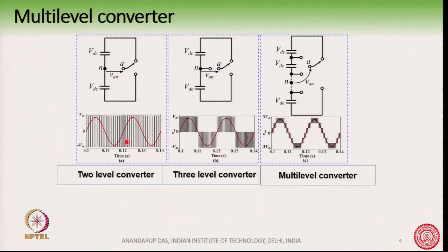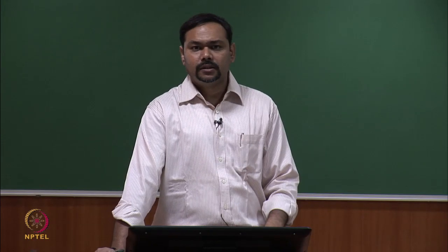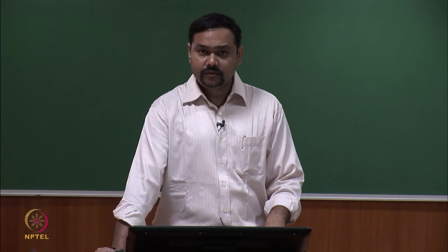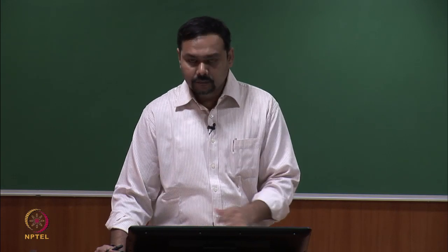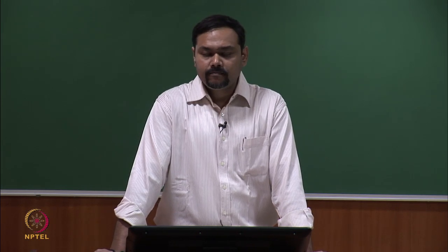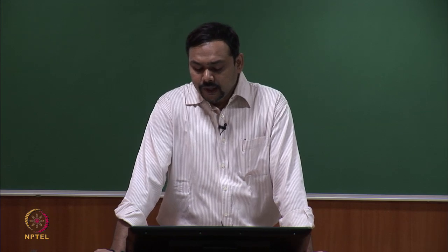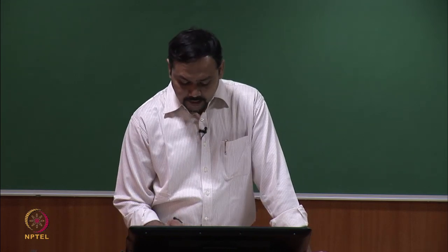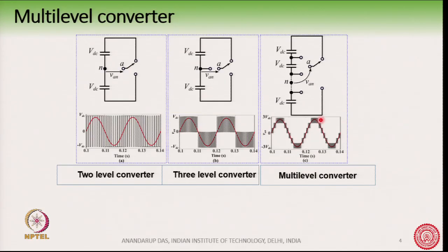We can get a voltage waveform which is very close to a sine wave. It is very useful for say motor drive applications, because if we get a waveform which is very close to sine wave, then we do not need any filters.